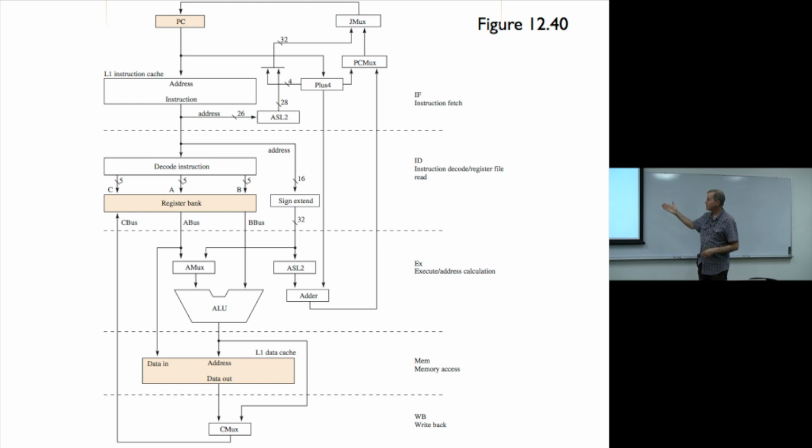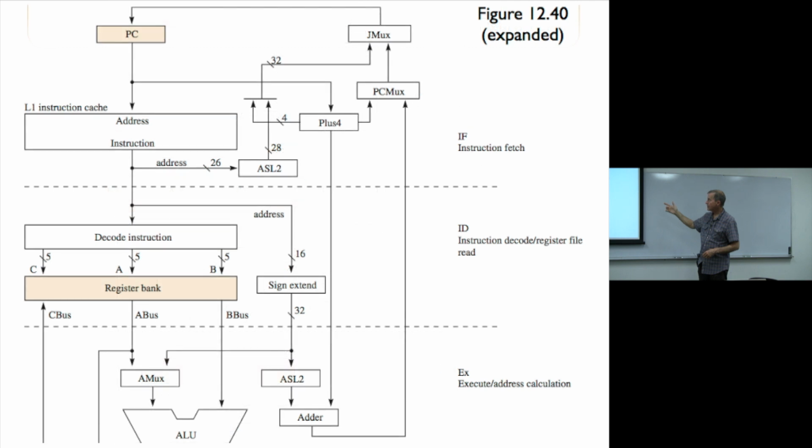an adder. Now do you see where the adder is for the program counter? Where is the adder? Is it the +4? Well, there's 2 of them. Yeah, and actually you spotted it correctly. That +4. Why do we have a special purpose adder whose only goal in life is to add 4 to the input and have the output be that input +4? Why do you suppose that we have a special purpose one to do that?